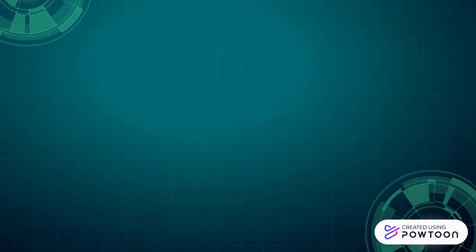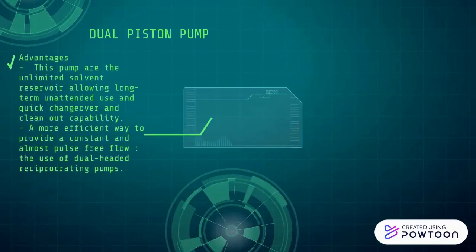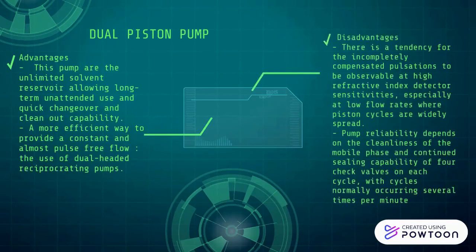reduces pump efficiency. For the dual piston pump, the advantage is that these pumps have an unlimited solvent reservoir, allowing long-term unattended use and quick changeover and clean-out capability. For the disadvantage, there is a tendency for the incompletely compensated pulsations to be observable at high refractive index detector sensitivities.